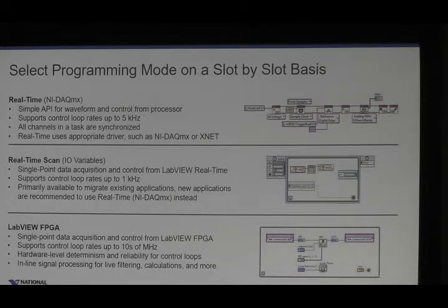And the answer to that is, when we talk about RSI in this case and not recommending it, it is specifically for the modules that are integrated into the controller. For existing things that use the scan engine for synchronizing things for motion control, or such as the EtherCAT chassis, some of the behind-the-scenes stuff that still exists in the programming experience will still be the same for those. And on the next slide, we'll actually even talk about a new expansion option for this that's, I think, really interesting as well for expanding beyond 8 slots.